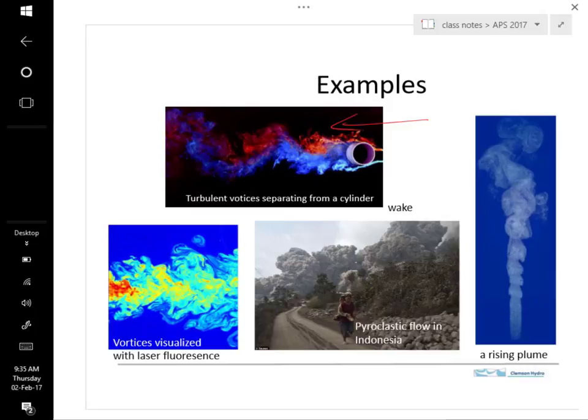or we can think of it as relatively static fluid and the body is moving. And so what you see here is two dye traces, or two dyed or traced fluids, that go past this body and mix. And we see these vortices. We also see kind of an oscillation downstream from this body. So we have a general big picture pattern, but then these smaller vortices that cause complications.